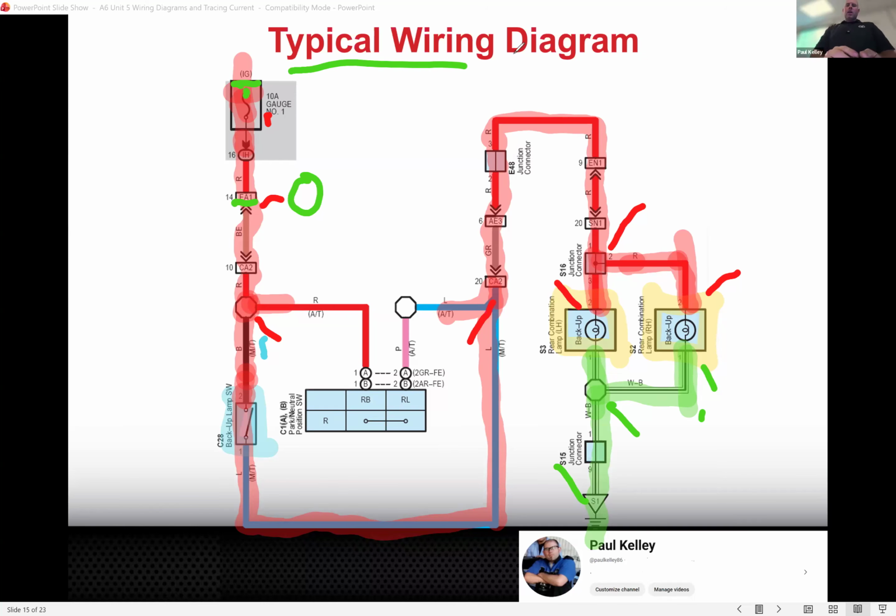But if my first measurement was right here and I got a 12, and then I got a 0 there, I'd say it could be the fuse. Technically, couldn't it be this connector right here? So we've got to get it all the way narrowed down. Let's go to this point, and let's say I agree with what Tracy said, and we've got 0 up here. Then we're pretty much at the fuse at that point. Wherever it goes from 12 to 0, it's between those two points.